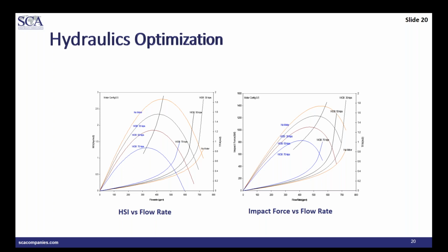The map you can see is completely different because the torque is dependent on the pressure drop, or the pressure drop depends on the torque on the mud motor. And also it is dependent on the configuration of the mud motor that we use. So you will see the weight on bit influence and the rate of penetration influence on the impact force, all the hydraulic horsepower per square inch.